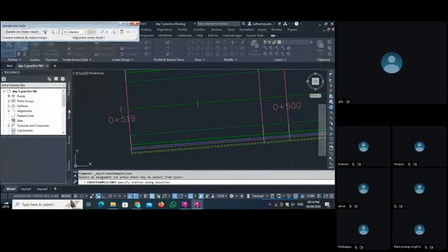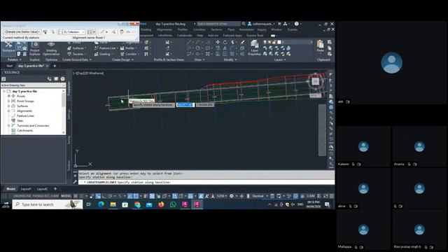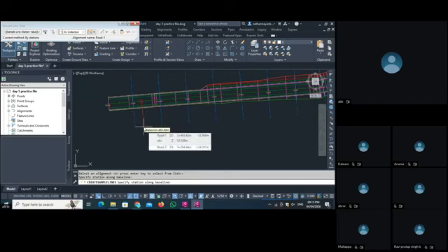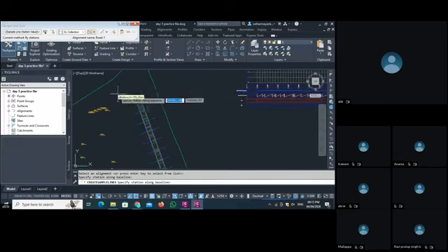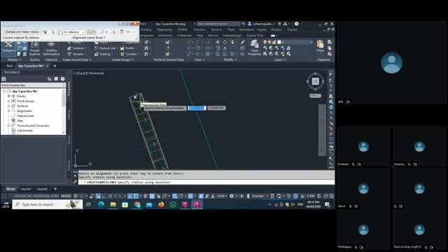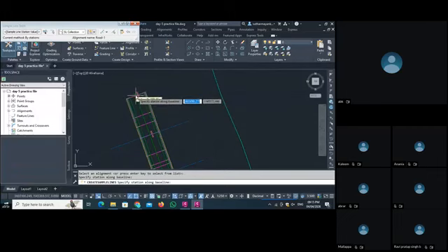Now we click OK. As we click OK, you see your sample line here. If you want to change the style, you can change the style. Now what they ask me is, specify station along baseline. So I want to set the station; my zero station is here somewhere. So I can click here, or I can say 0 and then press enter. Okay, and the width is okay, done. So our baseline is created.